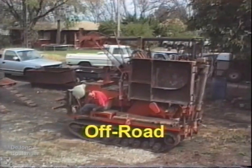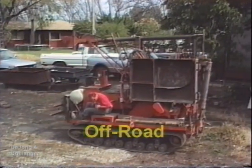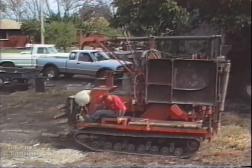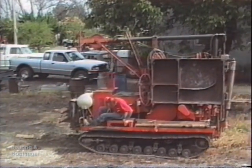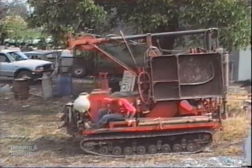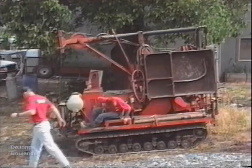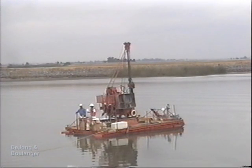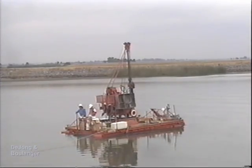Off-road drill rigs are used when access to a site is unusually difficult. Typically, these drill rigs are either mounted on large rubber-wheeled trucks or on tracks. If an off-road drill rig cannot directly access a site, a helicopter may be used to move it into position. For soil investigations beneath bodies of water, an overwater drill rig must be used. Some overwater rigs consist of a customized barge, where the drill rig is positioned in the center and drilling takes place through a hole in the deck.